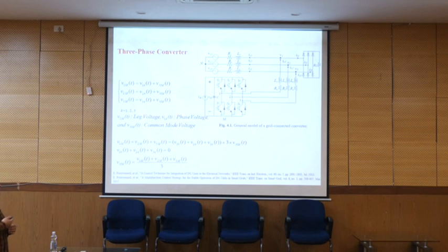The grid, we have a nonlinear load connected to the grid, we have the converter, then a filter, cable and transformer. So we have the model of the system, shown as the equivalent impedance of the whole connection between the converter and the grid. We can also represent the DG source as a current source.